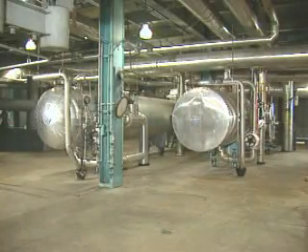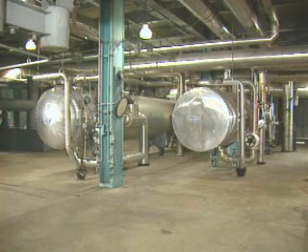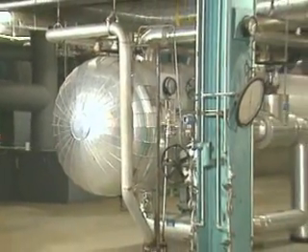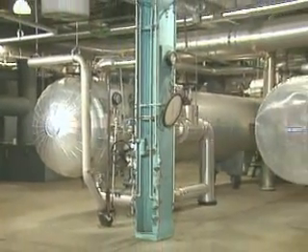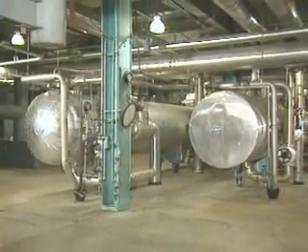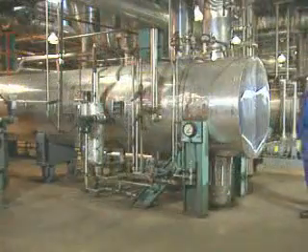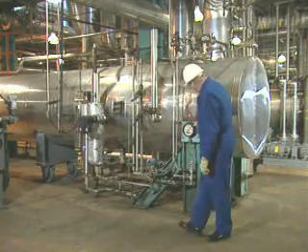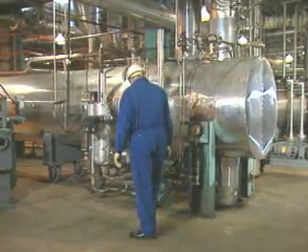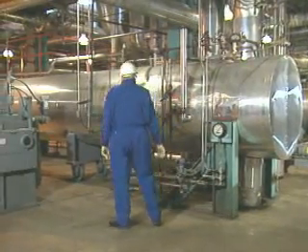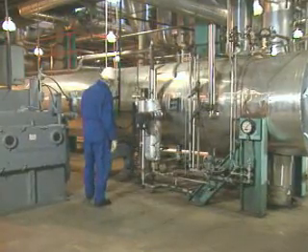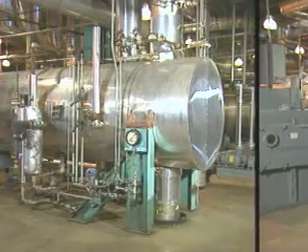A typical condensate and feedwater system has several shell and tube heat exchangers or closed heaters. Some may be used as condensers, but most are used as low, intermediate, or high-pressure heaters for the condensate and feedwater. The levels, temperatures, and pressures for all the closed heaters should be checked periodically during normal system operation to make sure that these operating variables remain within predetermined normal ranges.